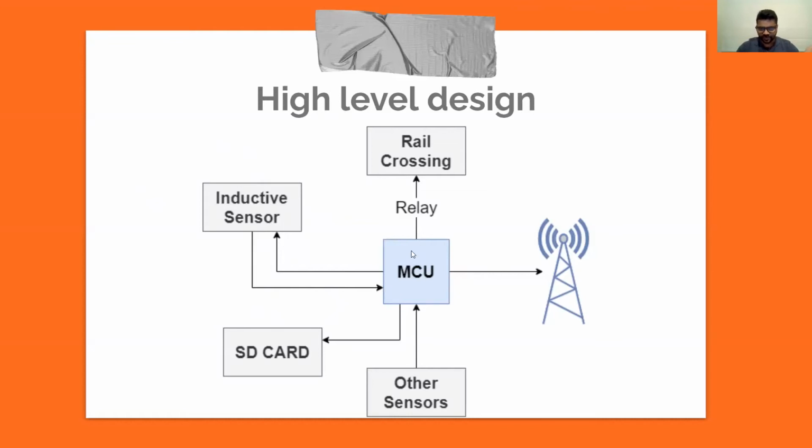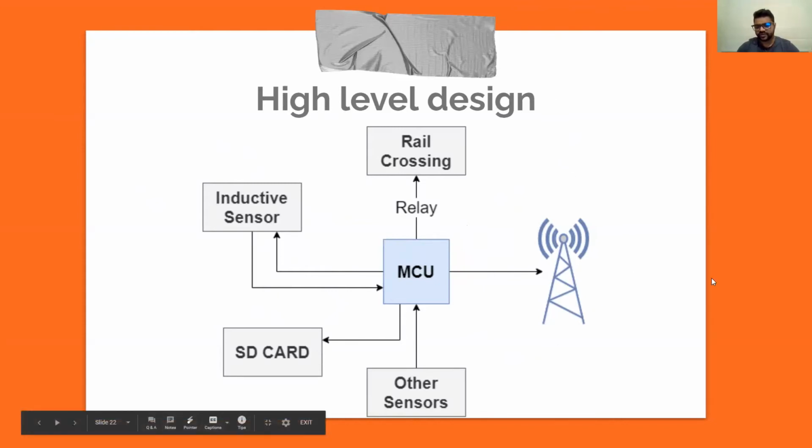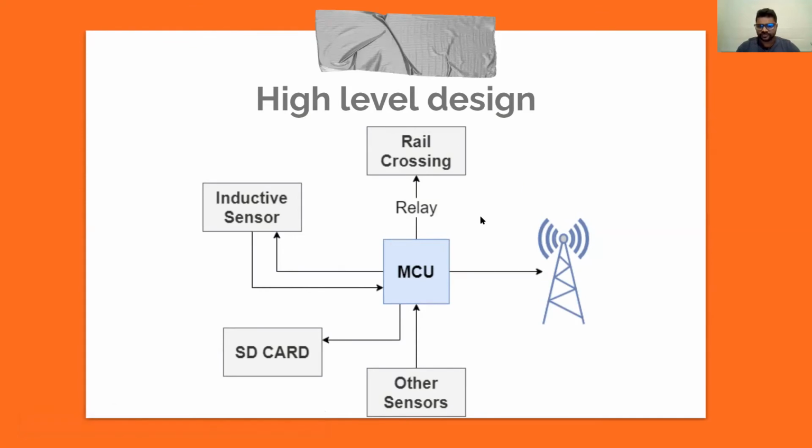And if we detected a train, we transmit that. Here I remember we had two radio modules for redundancy, because if one failed, the railway crossing wouldn't work. If one fails, a railway crossing located somewhere else might not receive the signal. So we transmit on both, and because of that at least one would be successful.